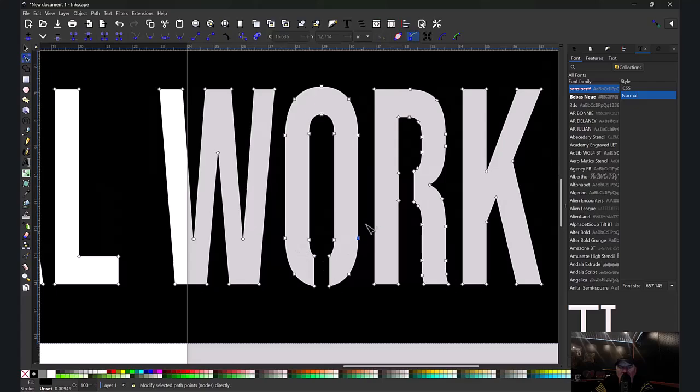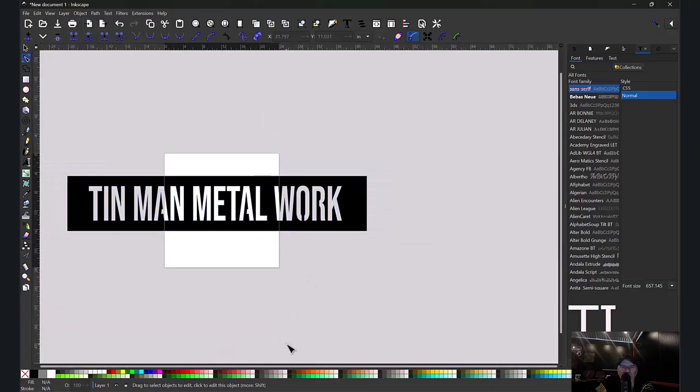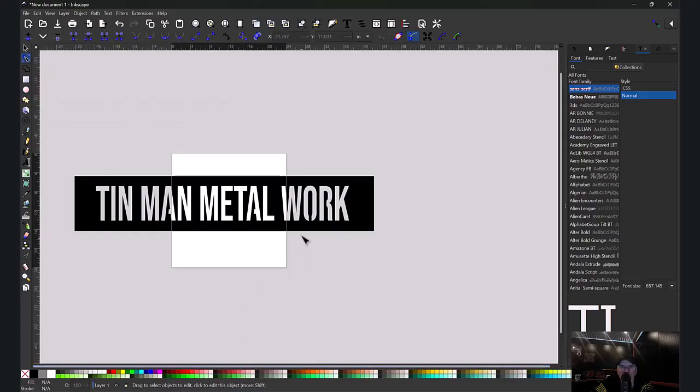The O we don't got to worry about. The R we do. So now we've got perfectly straight lines, and you can send that over to your table, and that will cut out perfectly. You want to get those nodes gone, because depending on how big you cut this out, it'll leave a little jagged mark there on your work, and you don't want that.